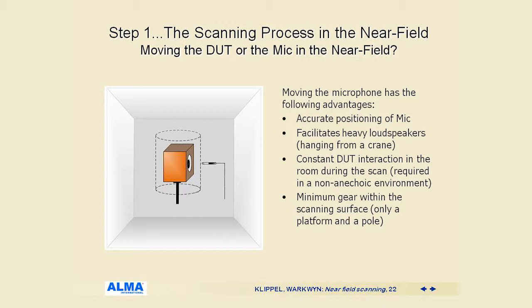You have constant DUT interaction with the room during the scan. This is important when we're doing measurements in a non-anechoic environment. We require minimum gear within the scanning surface. Only a platform and a pole. No rigging materials to support the heavy loads.